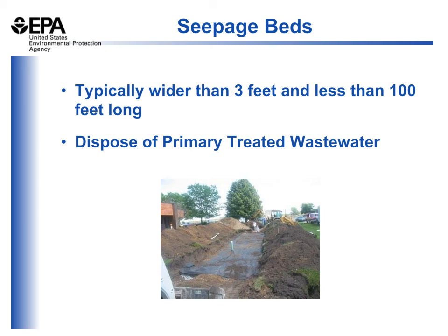As this slide shows, a seepage bed is built with effluent pipes running through washed gravel, which is then covered with a filter fabric, such that when the septic disposal field is covered with the topsoil that you see on the sides of the bed, the fine materials in this topsoil won't work their way down into the gravel where the effluent is being discharged.